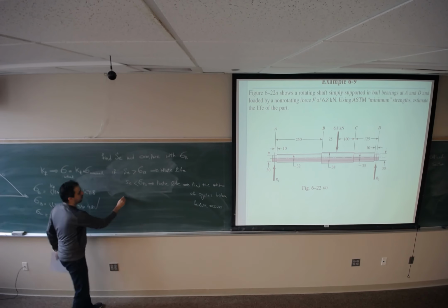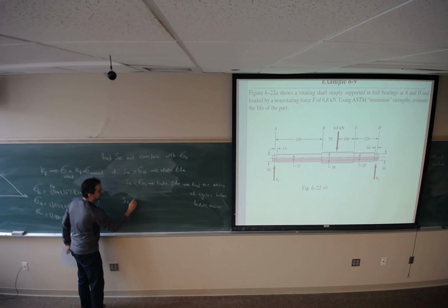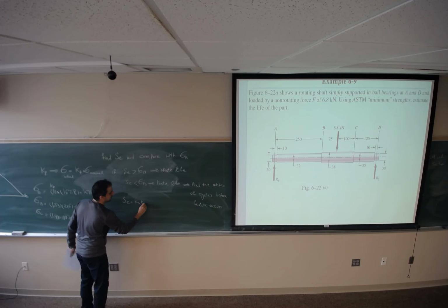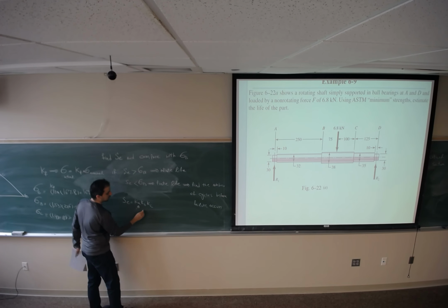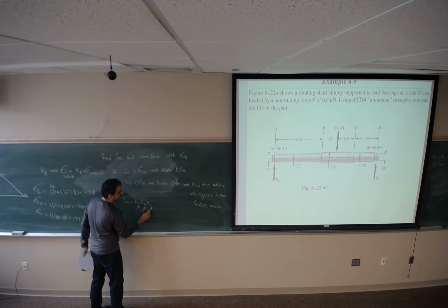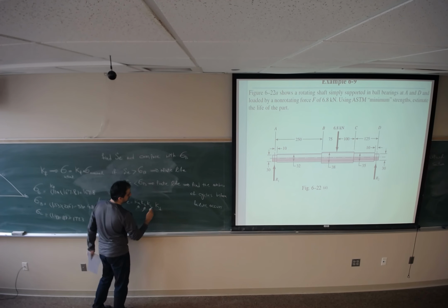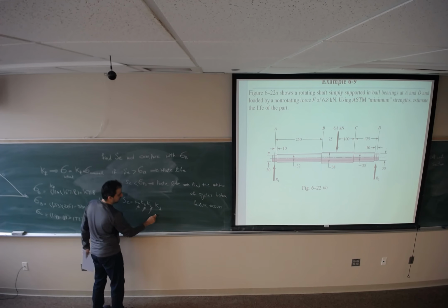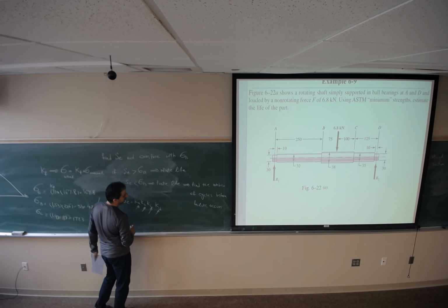To find SE, we should look at these factors: surface finish, size, load, reliability, temperature.